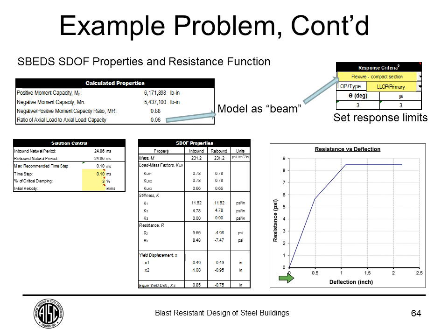And right here we have the resistance function. It is a fixed-simple element, so this first point in the plot is that first hinge that occurs at the fixed end, and then you have an additional strength until you reach that middle hinge at midspan when the collapse mechanism forms, and at that point you're just deforming plastically with no additional resistance.